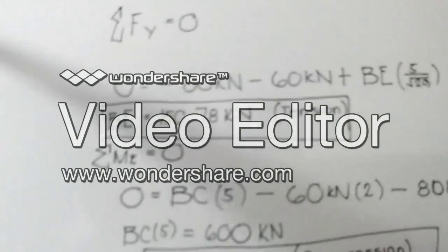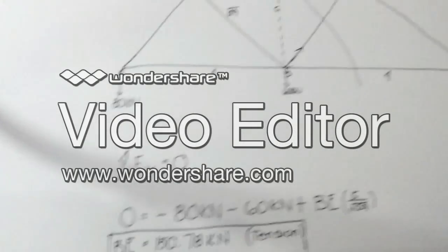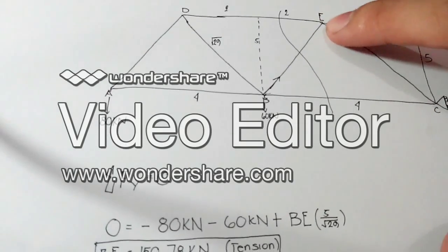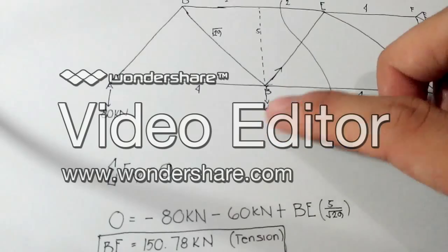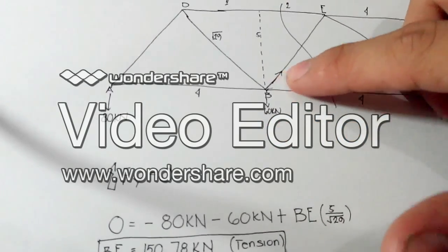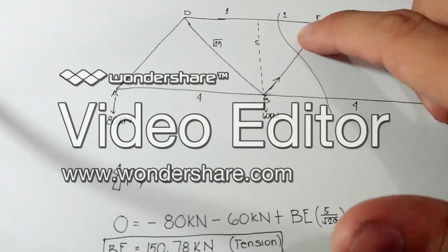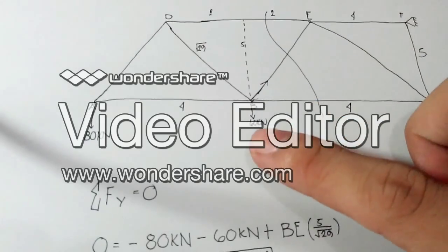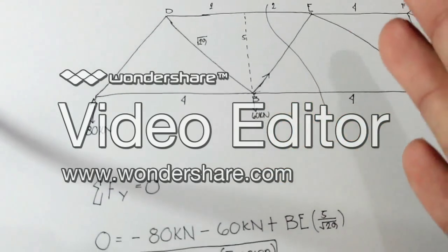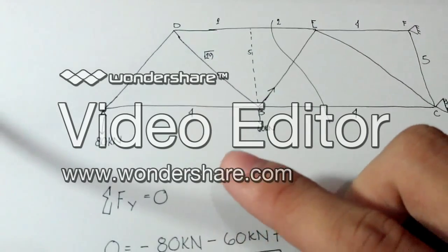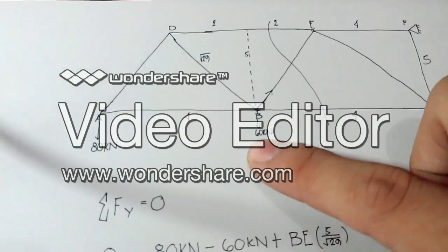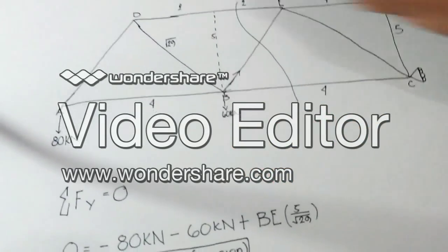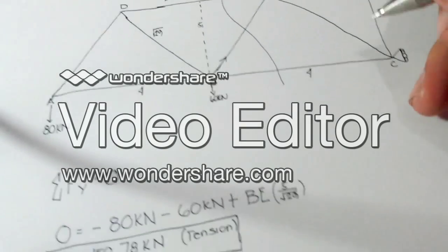So the next is we will use moment in E. So moment here in E. BE is not included because it passes through E. DE is also not included because it also passes through E. So the only forces included on the left section are 80 kilonewtons, 60 kilonewtons, and BC. I mean here. So here.